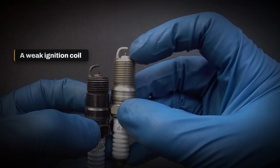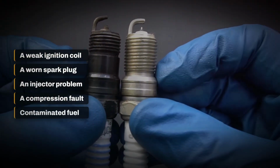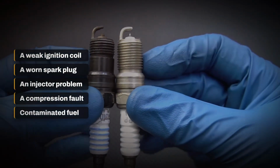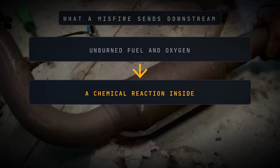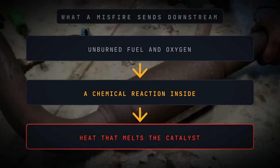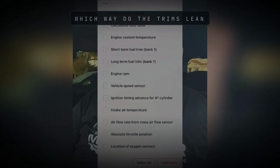A weak ignition coil, worn spark plug, injector problem, compression fault, or contaminated fuel can create an intermittent misfire. When unburned fuel and oxygen enter the converter, the chemical reaction can generate extreme heat. That heat can melt or damage the internal catalyst material. Next, look at fuel control.